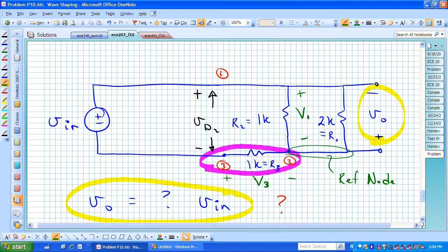And now we have two node voltages, and we would like to solve those. And if we were doing that, we would be saying, okay, what's the KCL at that point? And we would look over and see, wait a minute, we have a source over here, Vn, and we don't know what the current's going to be flowing from, let's say, right to left, from V1 to Vn. It will just be the current that source needs to supply.